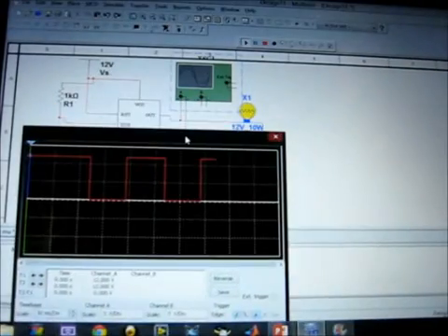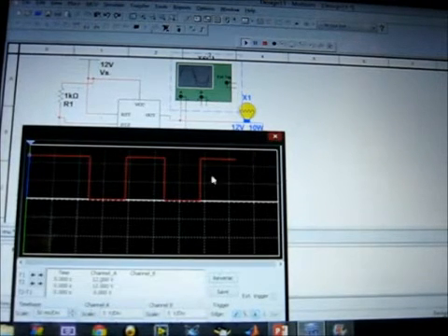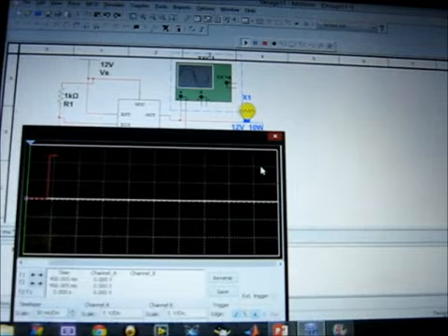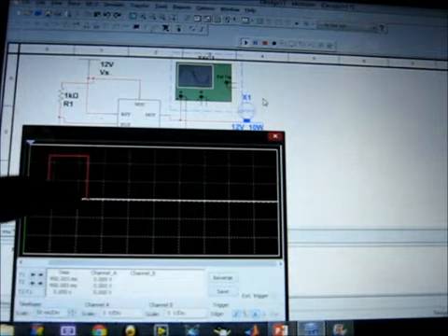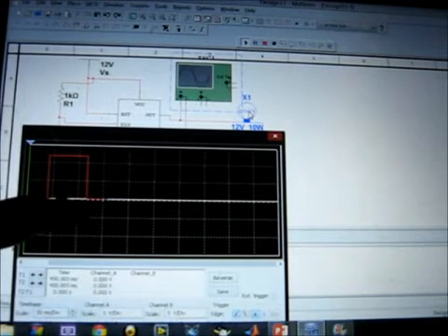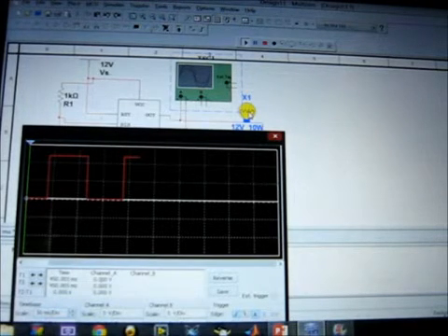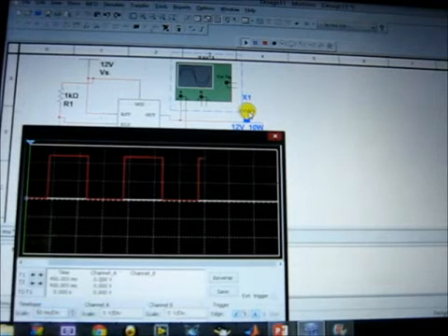You can see how this time differs, the oscilloscope is running, and when this oscilloscope line comes to this ground level, it is switched off. Now you can see it is switched on, the bulb is yellow in color. Suddenly the bulb goes off, that means this shows the off state. So this 555 IC is used to show the on and off state simultaneously, and these circuits are very readily used in our laboratories, in various experiments.